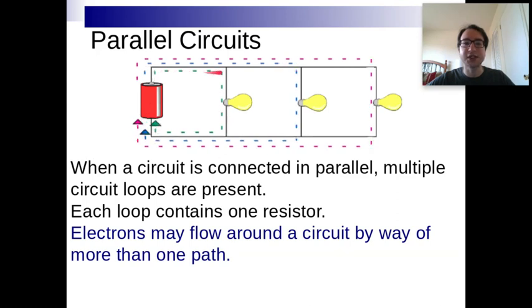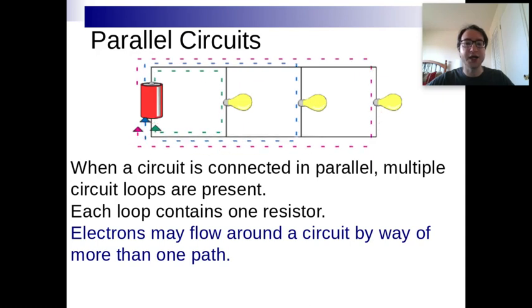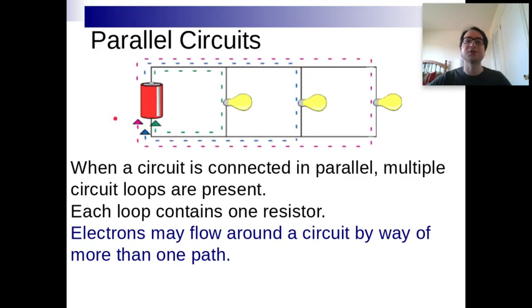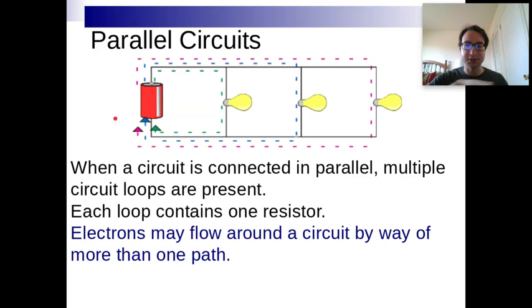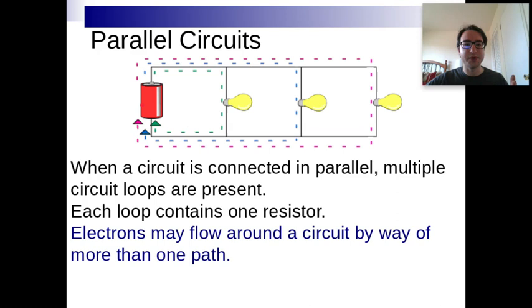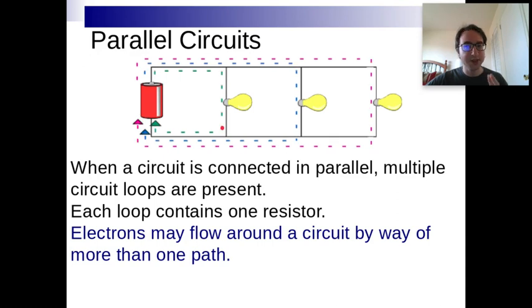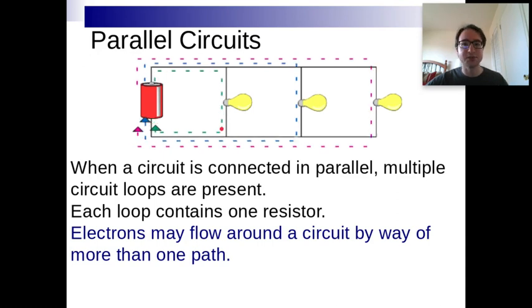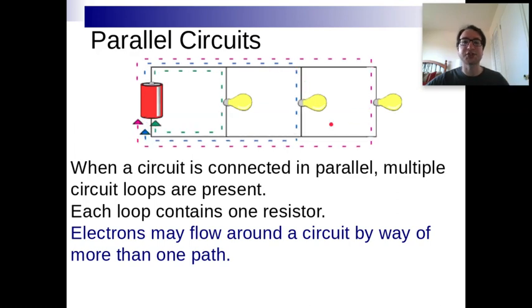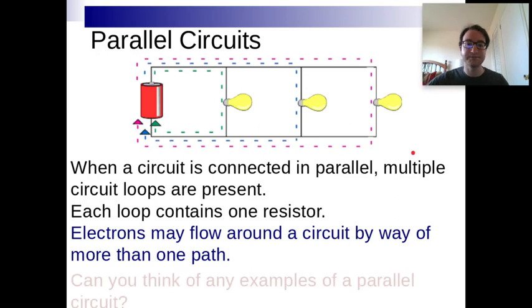You've given the electrons 3 options to go around the circuit. They're always going to make that circuit. They're not going to go one way and swing around backwards and do a couple of loops before going back to the battery. Electrons will always make just one trip around the circuit in one direction. And so since we've given them multiple pathways, overall, theoretically, there's actually less resistance because there are 3 pathways here rather than just one. Keep that in mind. We're not dealing with any equations for parallel this week, but it's a little bit counterintuitive that every branch you add actually gives you less total resistance.